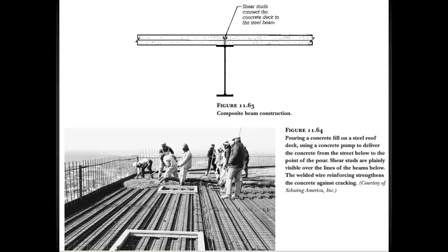These frames that are left out here may be what we call dunnage for holding a piece of air handling equipment, or it could be a future opening that they're going to cut through for an access door or roof hatch. You can see also these studs. These are called shear studs, and they're generally on the column line right above the beam, and they're used to help attach the concrete deck to the steel beam and keep it steady or keep it solid. So these are shear studs.